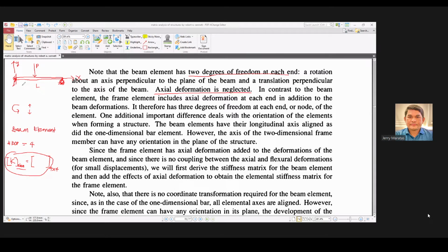That's also a prop beam, right? Now, assuming my load is inclined at a certain angle theta. This actually can no longer technically be called a beam. Why? Because our loads now, our member now carries an axial force, right?